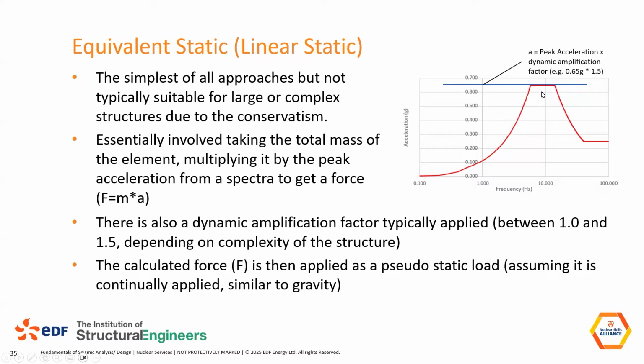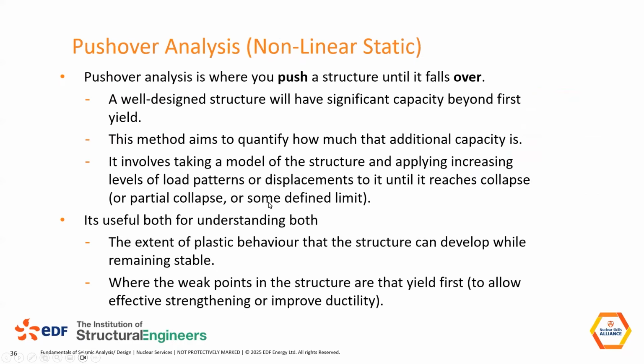We're taking the maximum acceleration. We don't know if our modes are here or how much mass is actually activated at this acceleration, but we're assuming all of it is, and then we're increasing it even further potentially with this dynamic amplification factor, and then design for that as a static force. So good because it's simple, bad, it's quite conservative. But that's equivalent static. If we stay in the static case, so again, we're not looking at variations of force with time.